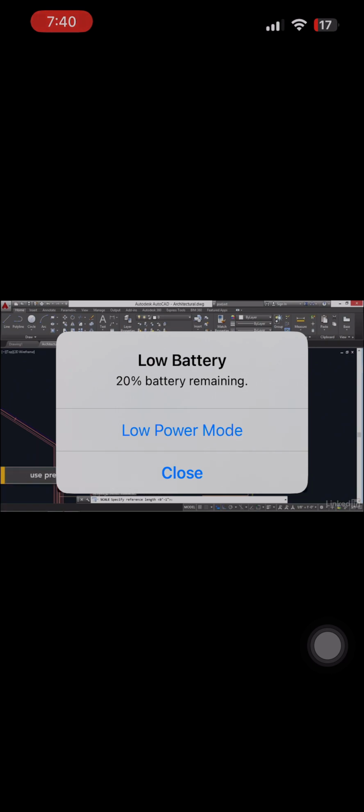Simply type the @ symbol and press enter. That's going to tell AutoCAD that I want to use the same point that I used before. Now the second point is going to be right here at the end of the table. For that, I'm going to have to snap to it. So I'll hold down Shift and right click and choose endpoint right here. Now you can see what's happening. I have the ability to scale this table up from the base point. And because I set that reference length as the full width of the table, I have really precise control over how that's going to be scaled now.